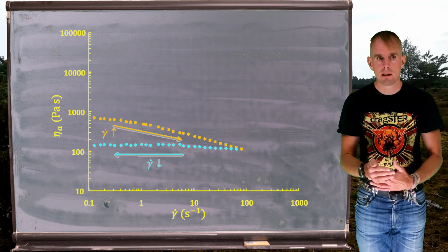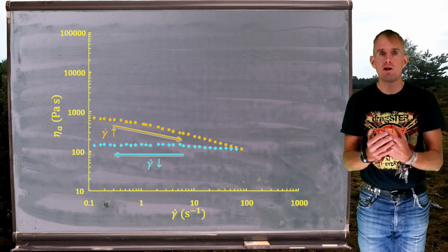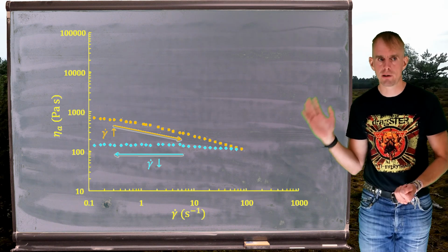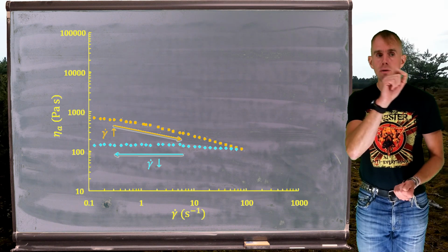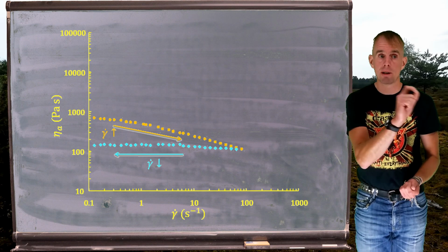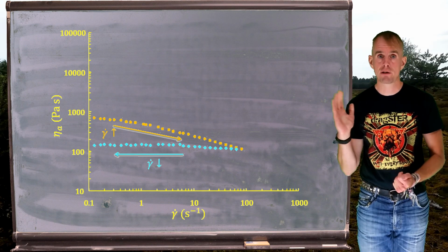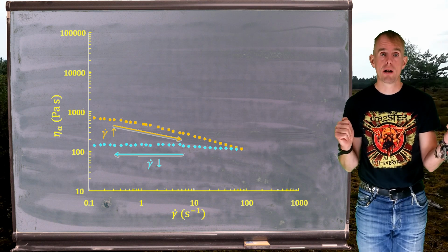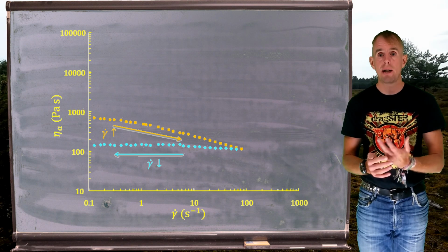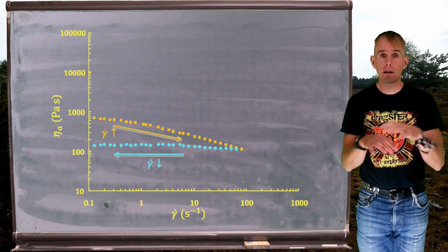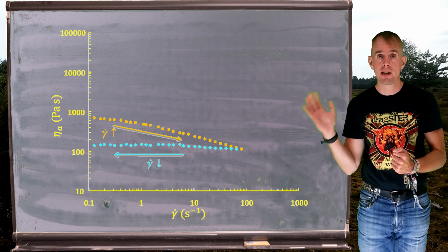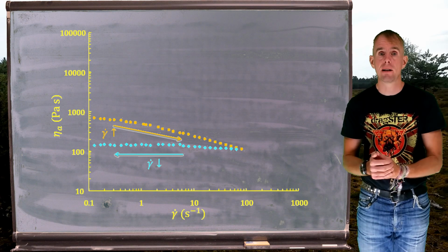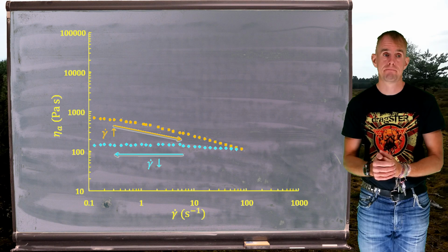There's no discernible difference in apparent viscosity as a function of shear rate. So what this is saying is that the material reformation timescale is far, far, far longer than the timescale associated with this experiment. Again, if I was to increase the shear rate immediately following that decrease represented by the blue data, I would probably get my Newtonian behaviour back. And so think about this for a piece of processing equipment. It may be possible that a shear thinning material might be behaving in a Newtonian manner because of this thixotropy.